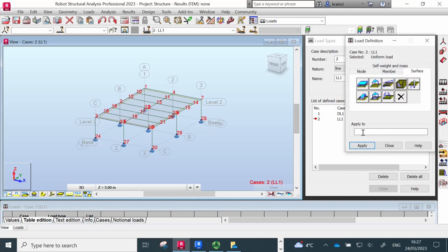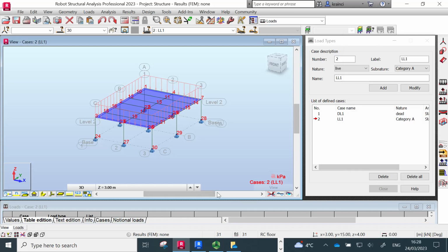Add and apply to the panel, which we can do from here. Panels all, we have just that 130, and apply. Close. So unfortunately, I could not get the load from Revit to work. If maybe you can try, and if it works, it's brilliant.